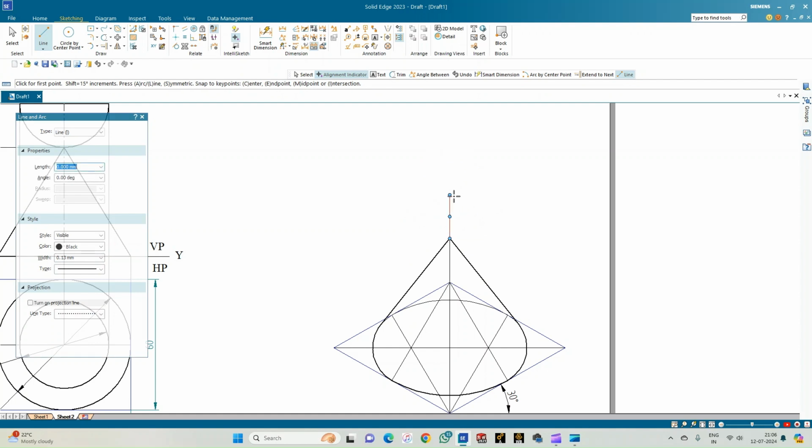Here again we need to draw the circle. So this is a line of length 20 mm. Again here draw 20 mm, the angle is -30. Similarly, from this point 20 and the angle is 150. So you get this line. In the isometric sheet, you will draw two boxes here, and from here two boxes, two boxes.